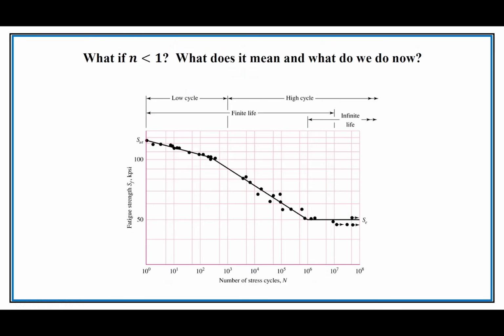So what does this mean if you have a safety factor below 1, where we've already mentioned that the thing will fail? That means it's not down here in that region. It means it's higher up, somewhere in here. So as soon as it has a safety factor below 1, it'd be a good thing to now predict how long it's going to live. So what we need to do is find an equivalent completely reversed stress so we can enter it into what we did in the last class, in class 10, to be able to predict failure.